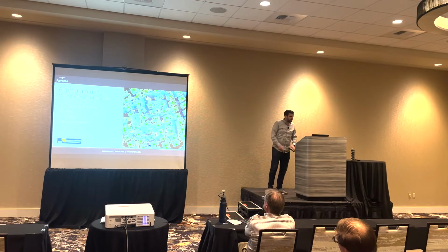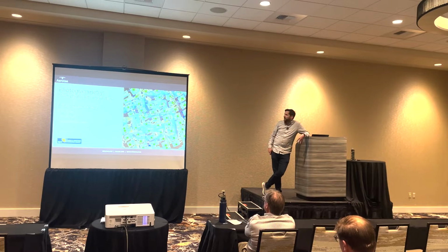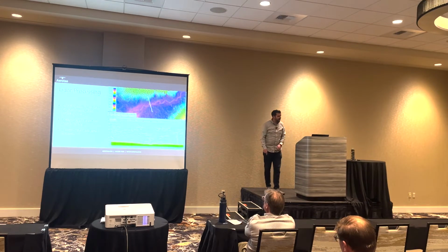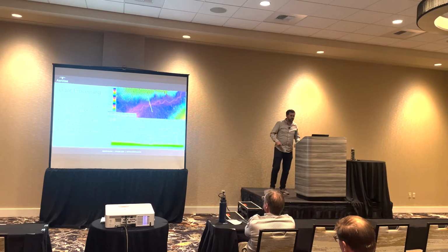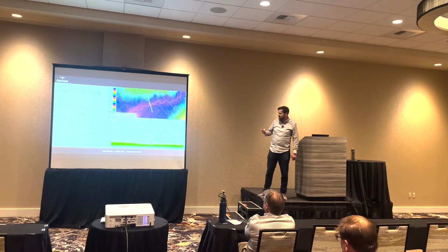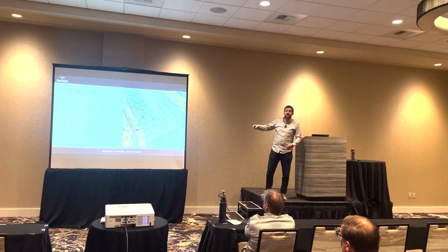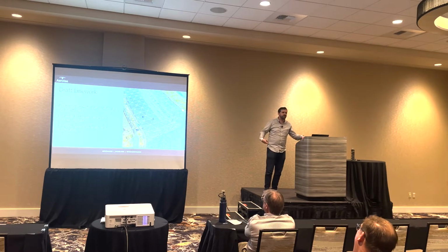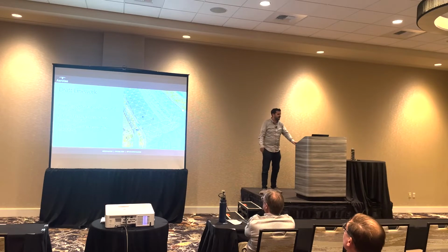So photogrammetry, that step is when you stitch the photos into those rich deliverables. It takes a bunch of photos and turns them into a point cloud, ortho photo, and digital surface model. I'm going into a little more detail on that whole process right now. Your LiDAR processing is when you classify it into ground, building, vegetation, creating your raster surfaces as well, and eventually your vector surfaces. Once you create all those raster surfaces, then you draft your line work. This is how you convert those big raster files into TIN files, into your vectorized files.